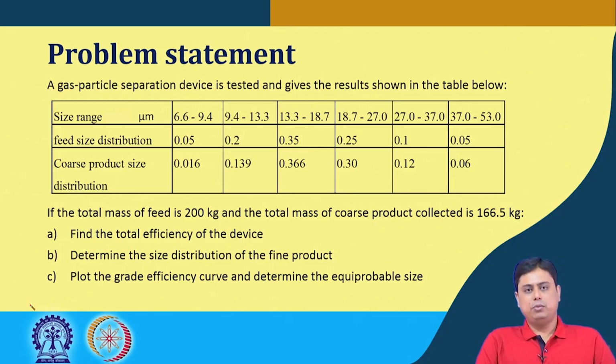determine the size distribution of the product, and plot the grade efficiency curve to determine the equiprobable size, that is x50, the value of x50.